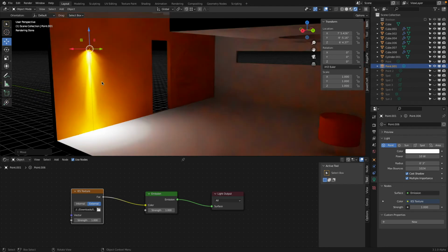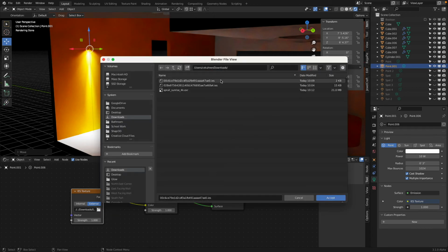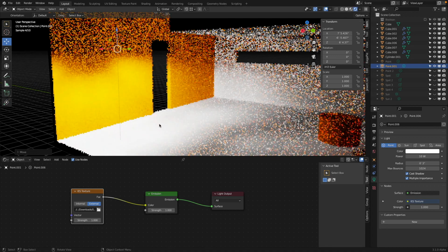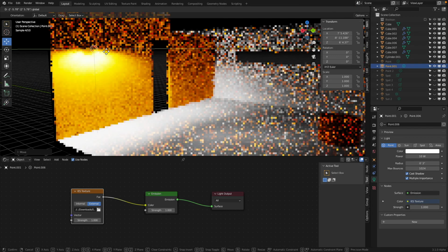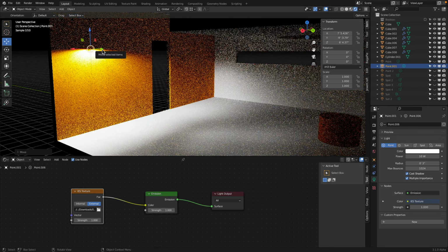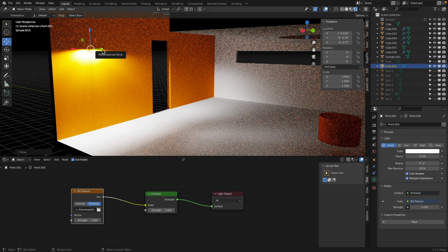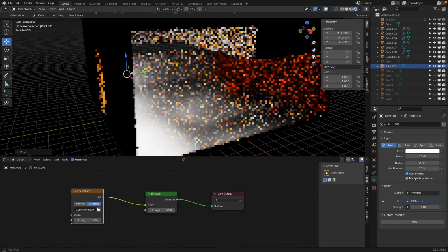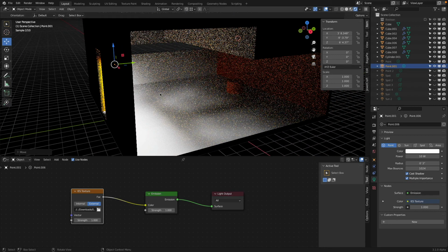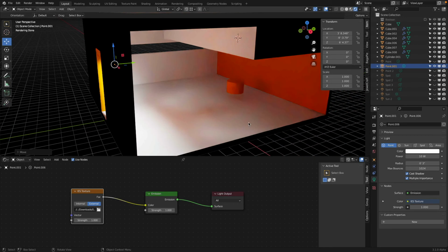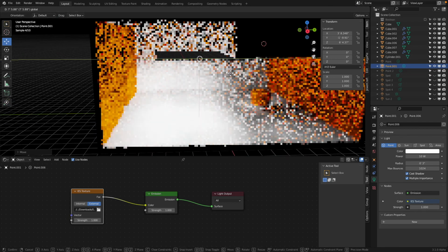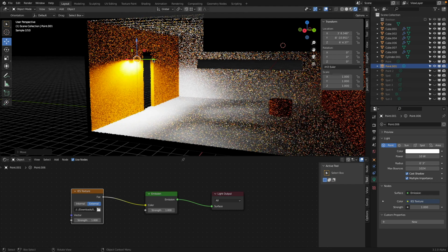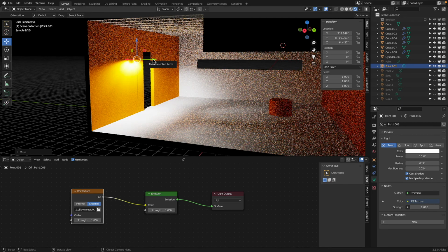And look at these really beautiful details. This is something you cannot create by hand. That's the reason why you work with these profiles, because the light is actually emitted, think about it, in a three-dimensional form. Maybe that's a good way to think about it. And look at the emission pattern even here on the floor. It's just not uniform. Okay, so these are the so-called IES light profiles.